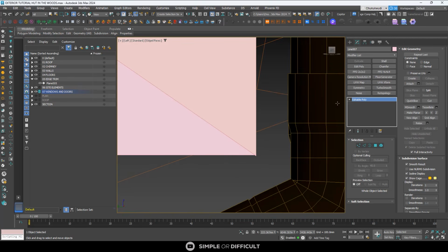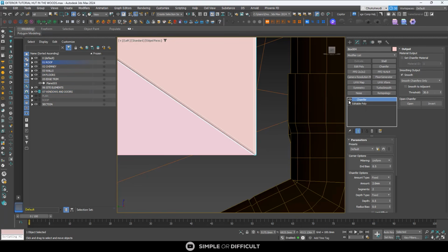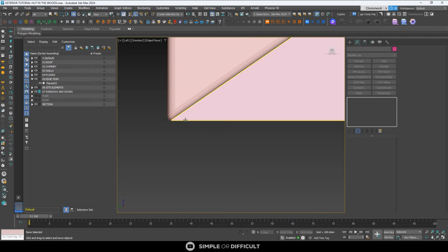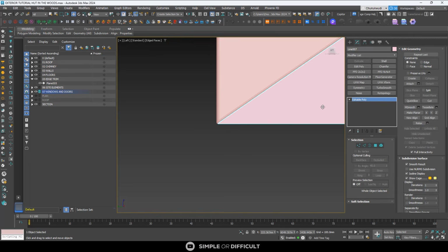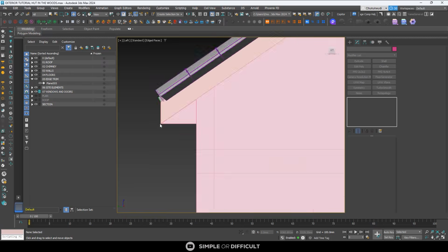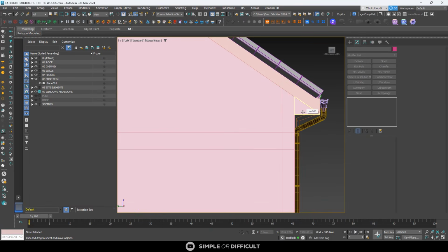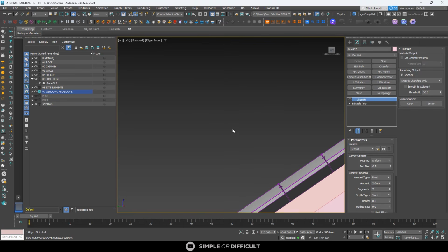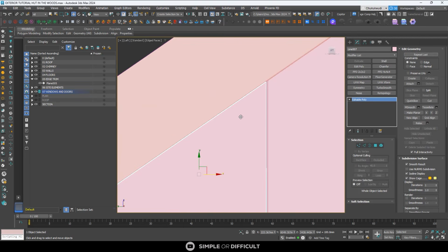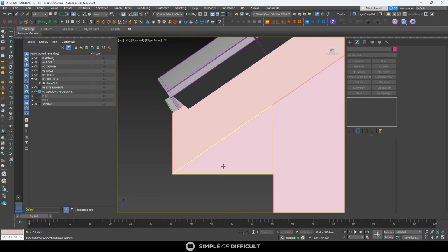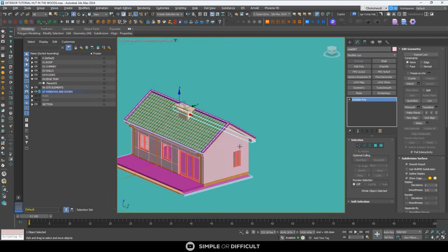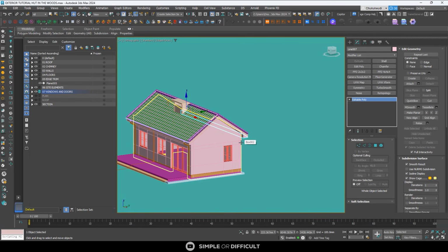So when I turn on this chamfer mode, you see it's going to chamfer those edges and everything is going to be all right. Good. The same thing. But I actually don't want to chamfer that one. It's just going to cover up that part and be a part of this roof. So it's okay if you don't actually chamfer that part. So yeah, we're done with the modeling.